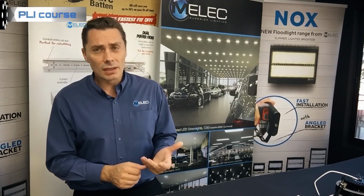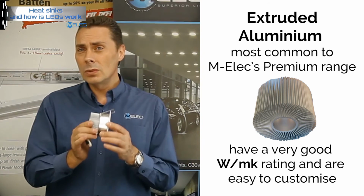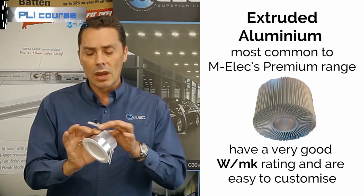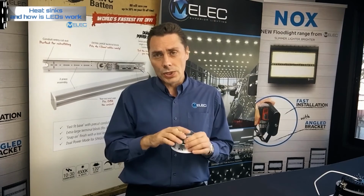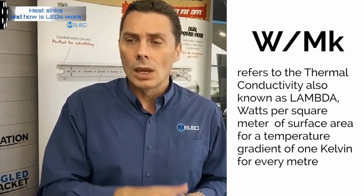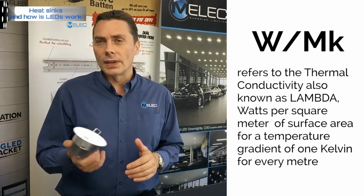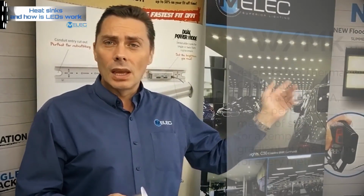Although not the cheapest heat sink material available, we have the extruded aluminium, and as you can see, I have one here. This you'll see on the majority of the M-Elec premium downlight range. It has a very fantastic W/mK rating, and these are also easy to customise. W/mK refers to the thermal conductivity, also known as lambda, in watts per square metre of surface area for a temperature gradient of one Kelvin for every metre thickness. Go back to the chart here, number 3.